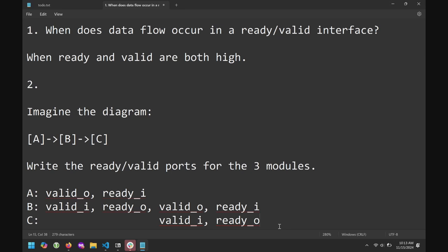Let me restate that. Remember, this is a parallel interface because we're sending single bits here, but at the same time we could be sending a 128-bit value, and it happens at the exact same time that both ready and valid are true. So we maybe have a 128-bit bus paired with this ready valid interface, and this is considered a parallel port because we are sending all of the data at the same time. That is totally reasonable on a chip because your wires and everything can get really, really small. So it's okay to have 128-bit buses that are super wide.